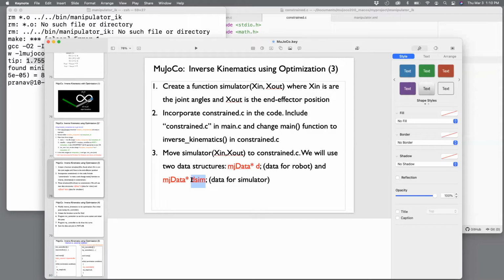But as you simulate, you need to find torques or control variables, and those control variables need to be assigned based on a model of the system. So you need a model of the system in order to find the torques, but you are already using the model to do a forward simulation. In other words, you need two models there. You need one model to do the forward simulation, and you need one model at every time step to do some computations to find the torque.